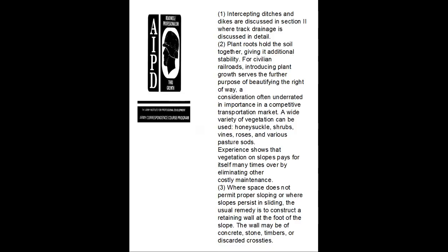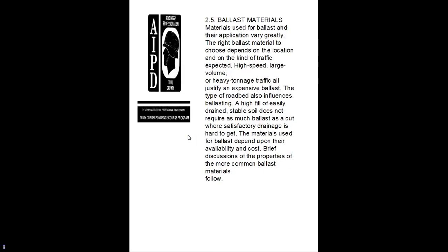Where the slope is not permanent, proper sloping is needed. While the slope persists in sliding, the usual remedy is to construct a retaining wall at the foot of the slope, which may be made of concrete, stones, timbers, or discarded cross ties.